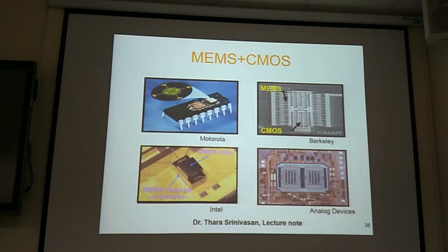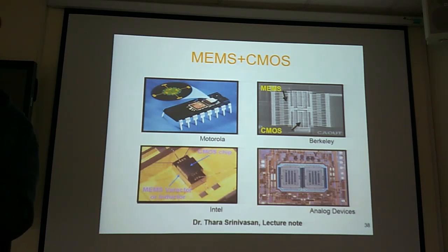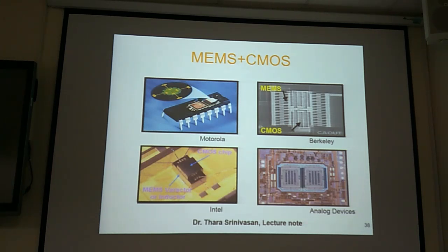Remember, for any mechanical structure, we need the circuit. We need the circuit to sense and to have the voltage output, because with a voltage signal we can use all the electronic instruments to measure the output. So we need a voltage signal output. Then the micro device is very small. For a pressure sensor, if the signal output is very small, we need a circuit to amplify the small signal.